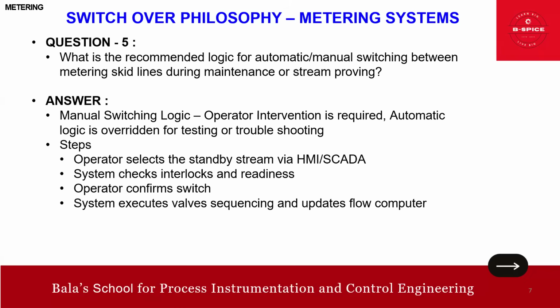But before that, I also want to give you some safety and interlock considerations during this switchover philosophy. Friends, no two streams active simultaneously, unless designed for parallel operation. Interlocks to prevent switching during proving or calibration, fail-safe logic in case of valve or instrument failure, and alarm generation for an unsuccessful switch attempt. So these safety and interlock considerations we need to focus on.